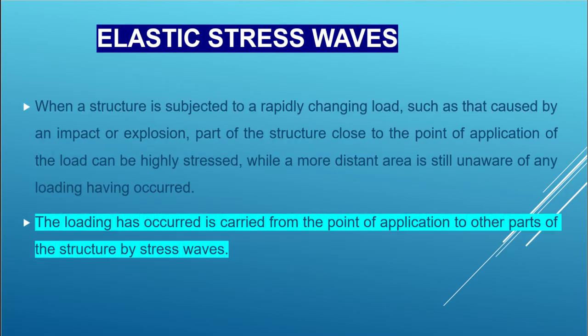And this one is important, elastic stress waves. And here I have already mentioned, when we apply a large amount of deformation for a short interval of time, stress waves will be developed. And the next question is, what are elastic stress waves and what are its classifications? So as I mentioned earlier, when a structure is subjected to a rapidly changing load, which is caused by impact or explosion, the part which is close to the point of application of the load can be highly stressed, right?